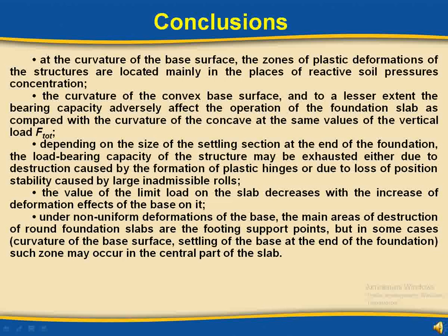Depending on the size of the settling section at the end of the foundation, the load-bearing capacity of the structure may be exhausted either due to destruction caused by the formation of plastic hinges or due to loss of position stability caused by large inadmissible rolls. The value of the limit load on the slab decreases with the increase of deformation effects of the base on it. Under non-uniform deformations of the base, the main areas of destruction of round foundation slabs are the footing support points, but in some cases, curvature of the base surface, settling of the base at the end of the foundation, such a zone may occur in the central part of the slab.